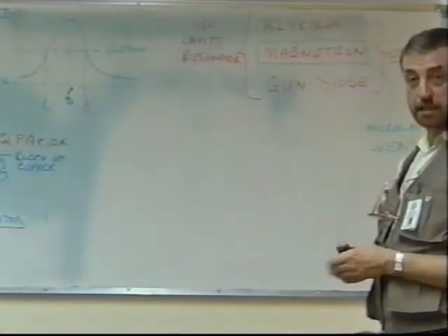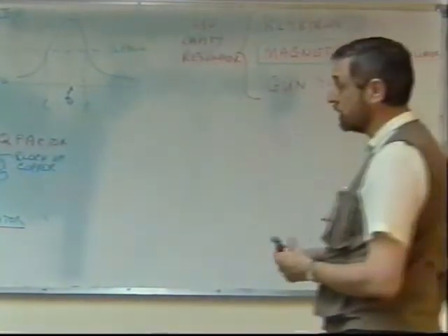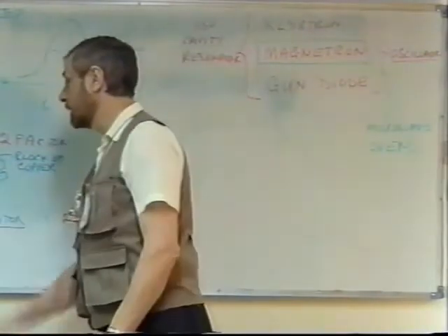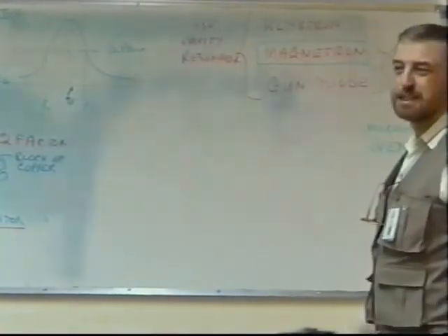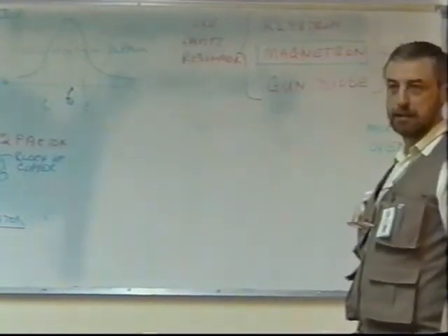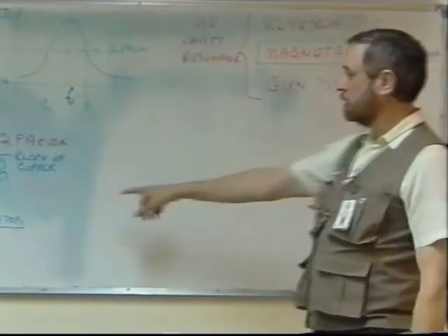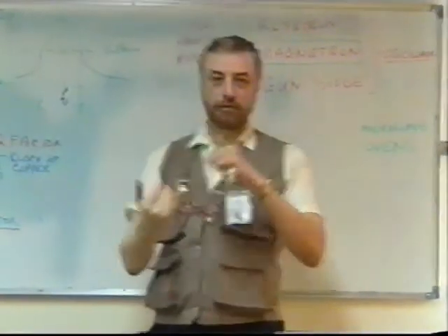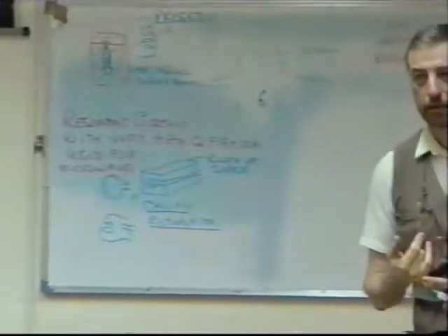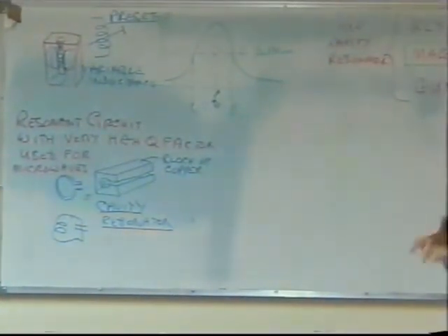Smaller the values of L and C. When we get onto the microwave side of it, we have to start talking about cavity resonators. So specially designed oscillators are made. In most oscillators at lower frequencies, you have a tuned circuit, you'll have a transistor or op-amp or something, feedback components, biasing components. If anything goes wrong with those, you can change any individual component.